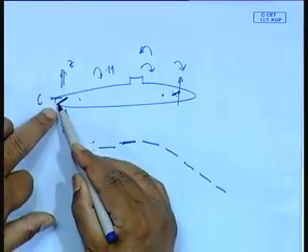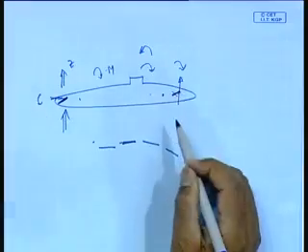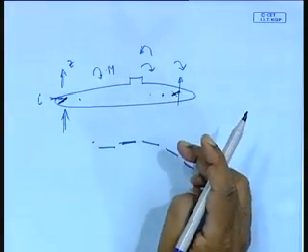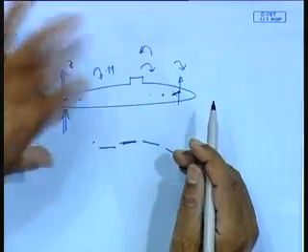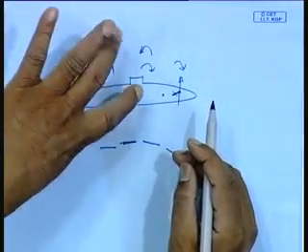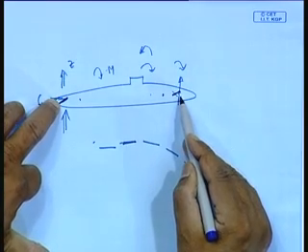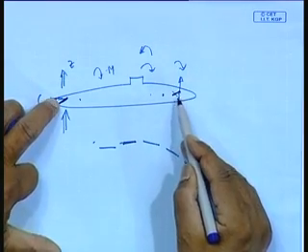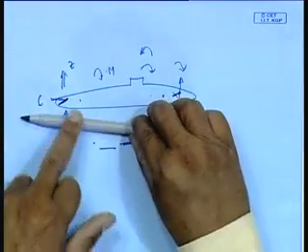Then why do you keep it aft? Because obviously for the same small angle the leverage you get is more. That is the same reason why rudders are kept at the aft end of a ship. You get much higher leverage, more effectiveness, to bring it down. So, normally in submarines these two planes are used for various purposes. One is to maintain depth. Sometimes, supposing you want to go down without a trim, just go down like that.